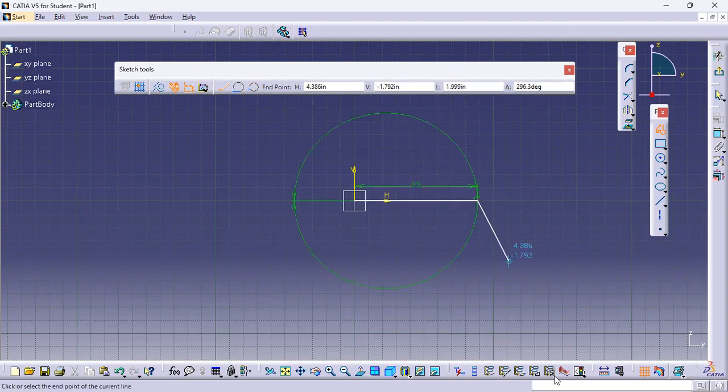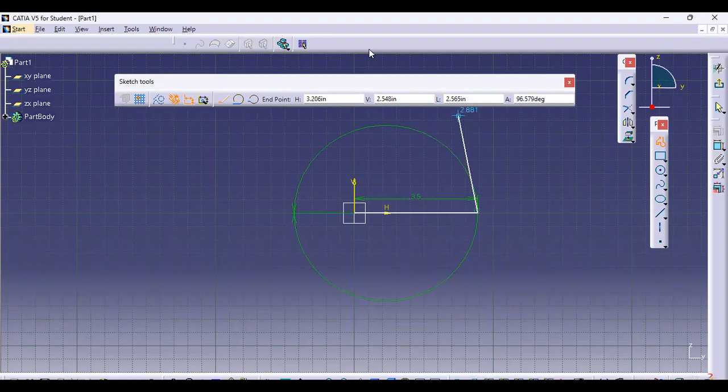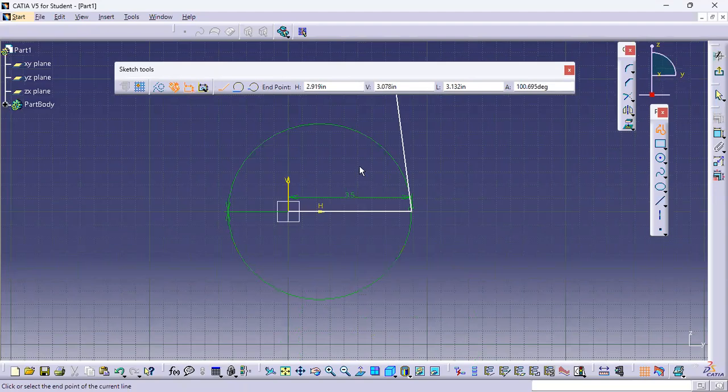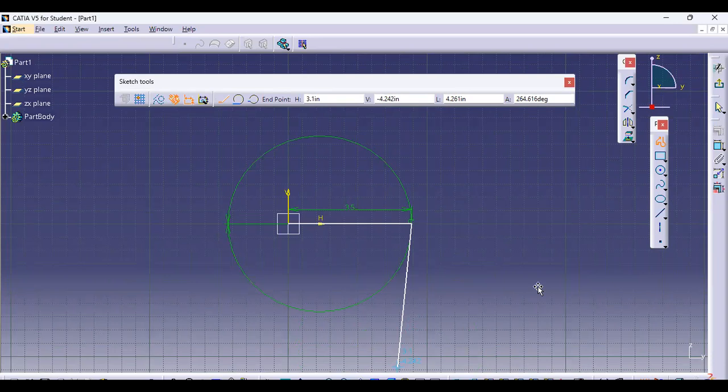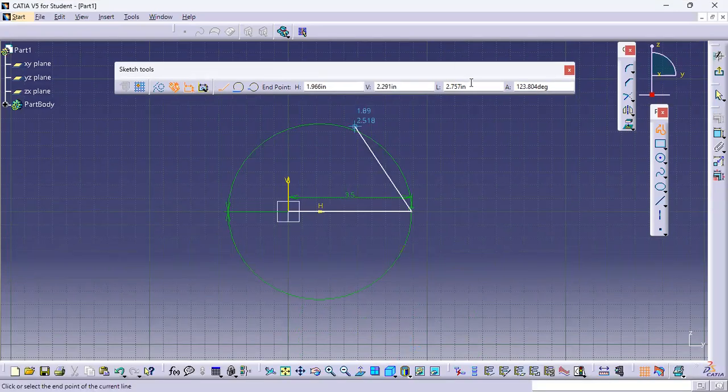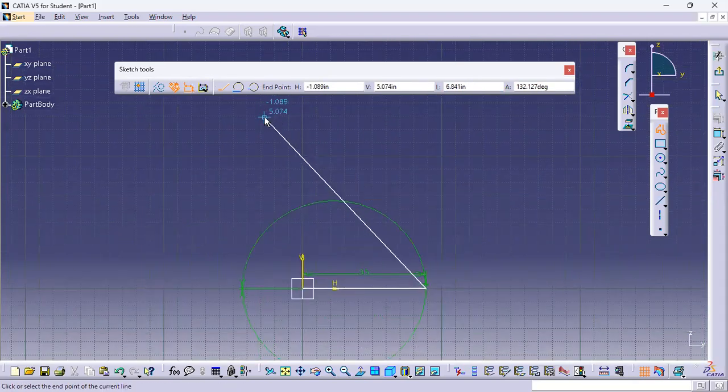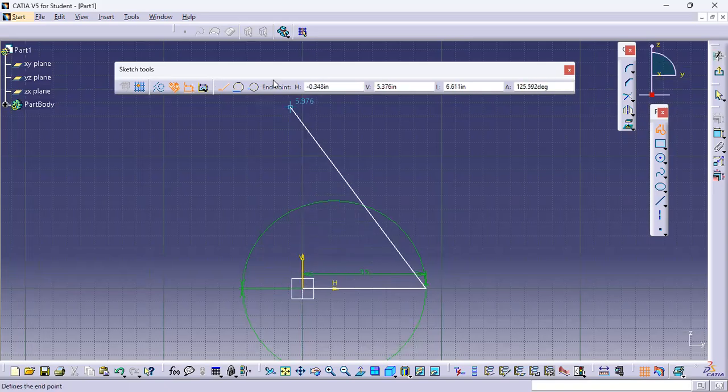And then I'll draw this inclined line, which is 60 degrees, as given in the isometric view. So I'm just going to pick a random length. You don't have to worry about the lengths, but make sure it's large. We're going to trim that later. So I'll pick this randomly somewhere. Make sure it crosses this vertical line. It isn't necessary, but just make sure to do that.